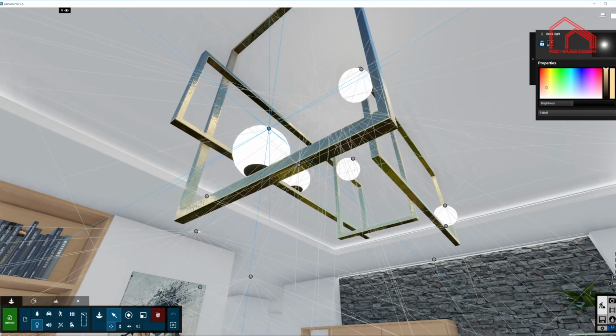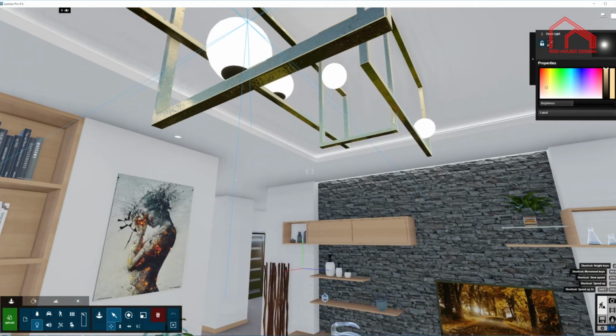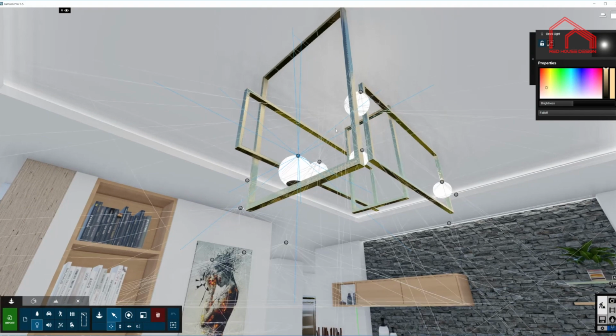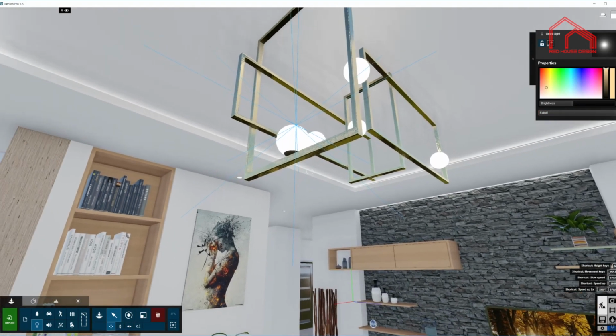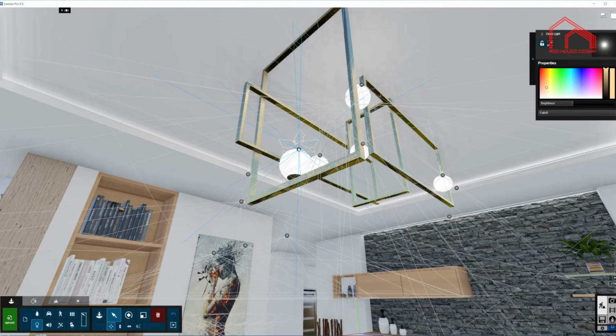This is the light that is emitted from the light source in 360 degrees, basically all over the place from the source. The advantage of this light is that it lights up the scene very quickly and very evenly, but the disadvantage is, once again, it penetrates the material and also does not cast shadow. So once again, you have to work with the brightness and the fall off very well to get your desired effect.